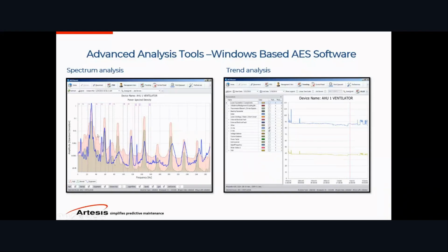For instance, if you were to have an unbalance issue, you would see a one-times RPM of the rotational speed plus and minus the line frequencies. And I think a lot of the vibration people can be easily acquainted with this approach here and analyze the spectrum if needed.